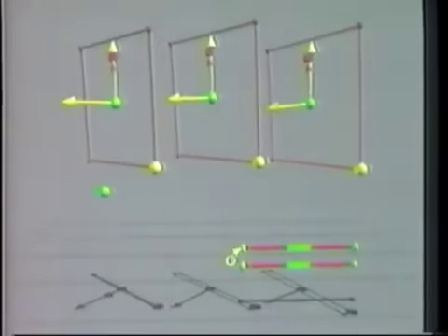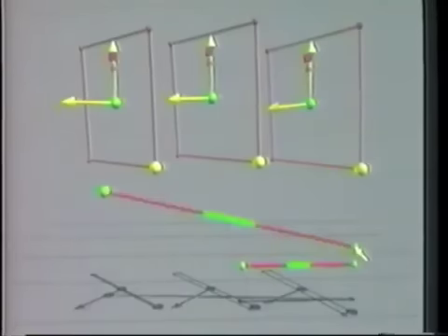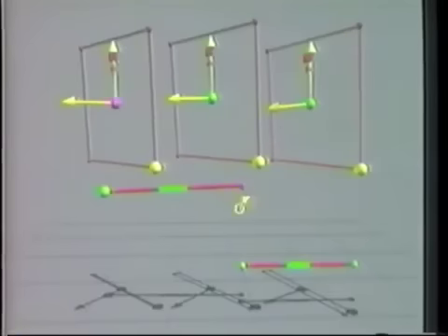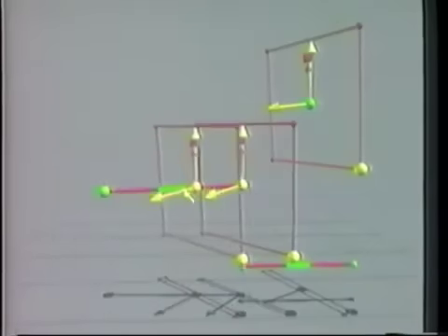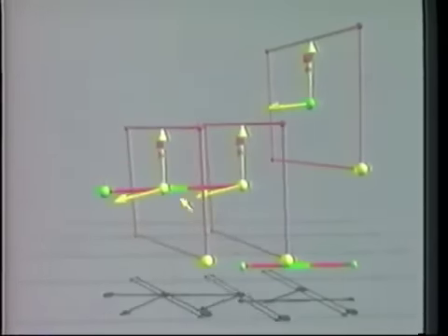First, a point is used for the center of projection. A length widget serves as the viewing axis. We link the center of the plane to one end of the length. This will be the film or projection plane. A second plane, used for the front clipping plane, is linked both to the length widget and to the up and normal vectors of the film plane.